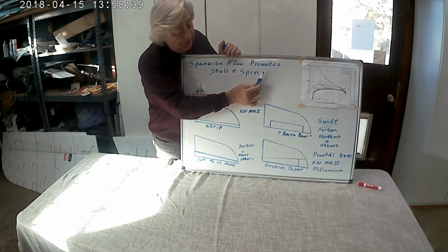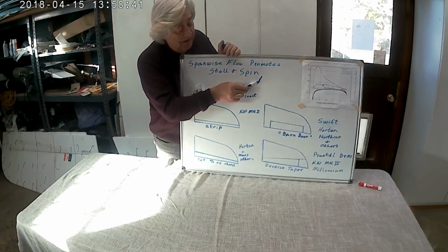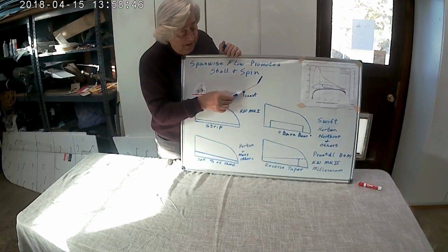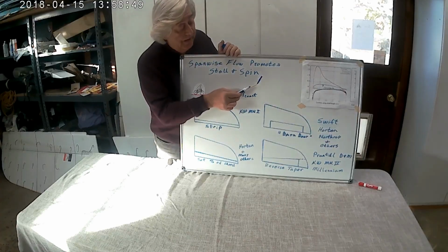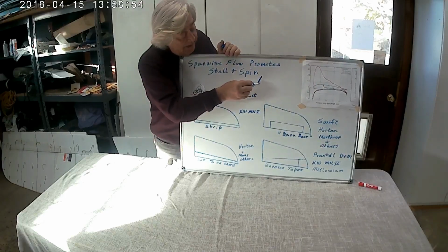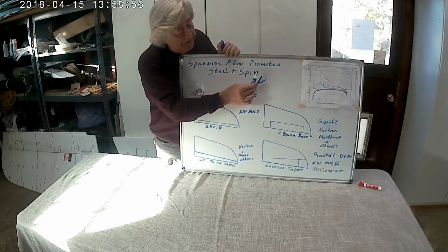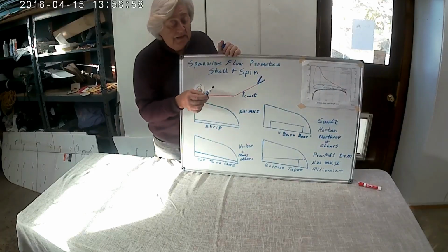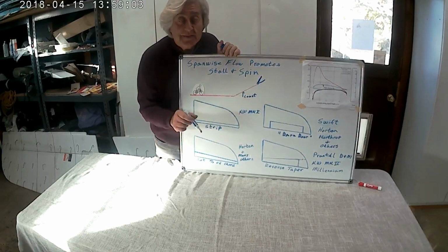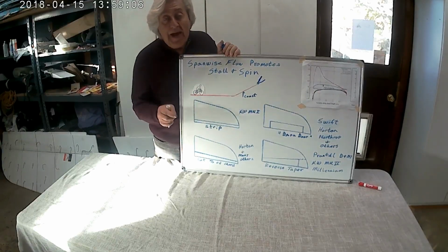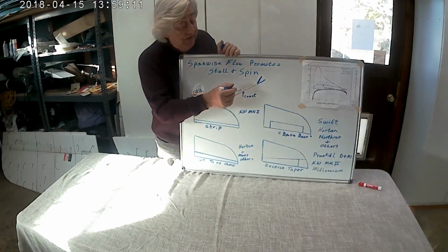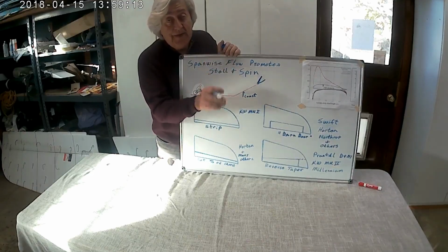So you stick up a control surface like this, and the air's coming along, and it can't get up that hill. There wasn't enough speed stored up here to get him past us. If it's a little deflection, oh yeah, he might make it. But if it's enough deflection, he can't get up and over that hill because he has insufficient momentum. Remember, momentum is mass times velocity. So he has a set velocity here and he has a set mass. So he's only going to go just so far, and that's it.